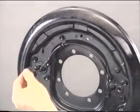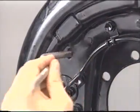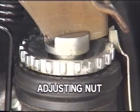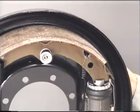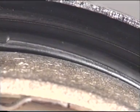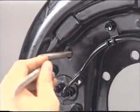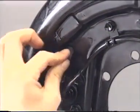Remove the shoe adjustment plug from the packing plate. Turn the adjusting nut using the SST until the wheel locks. Turn the other end of the adjusting nut using the SST until the wheel can be turned easily. Refer to the repair manual for the standard number of notches to be backed off. Repeat this procedure for all the other wheels. Install the shoe adjustment hole plug and the operation is completed.